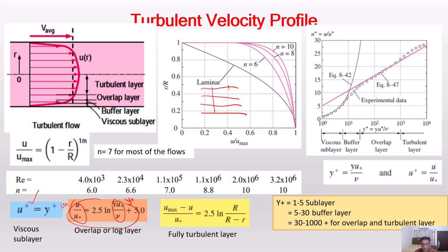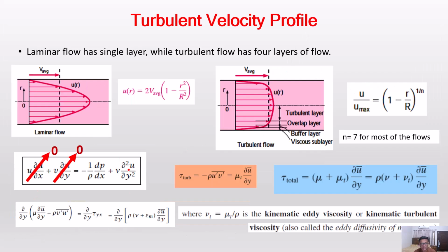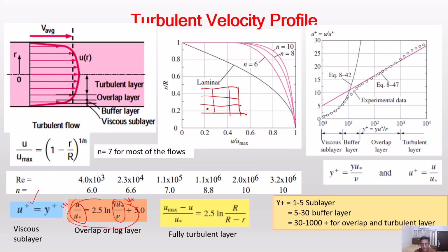So what we are doing is solving the momentum equation on these cells. If you are directly on the wall, the no slip condition is provided from the wall. But the first cell height is not exactly on the wall. In finite difference, the first node will be on the wall, but that's a different thing. In the finite volume, the first cell is not directly on the wall. So how do we find out the value for this first cell?